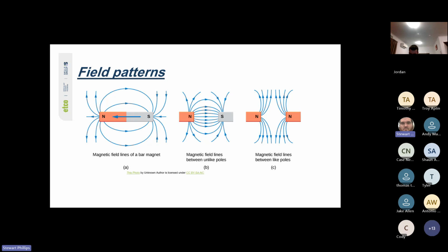So there's no EMF when the magnet is not moving, because there is no change in the magnetic field. If it's not moving, it's not cutting across and therefore not inducing a voltage. So if the magnet sits still inside the coil, there's no change in magnetic field. It's the change in magnetic field that induces the EMF. So only as we alternate or change the field is the voltage induced, which is how generators work: they're constantly moving to generate an EMF.